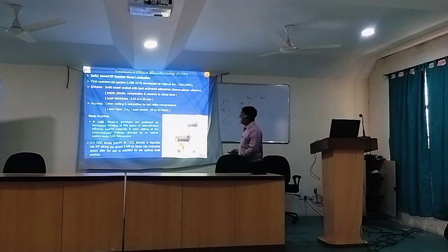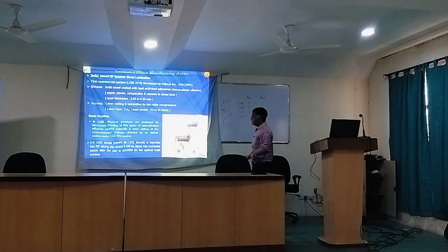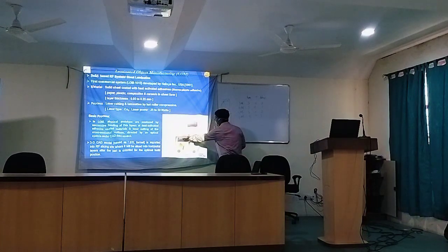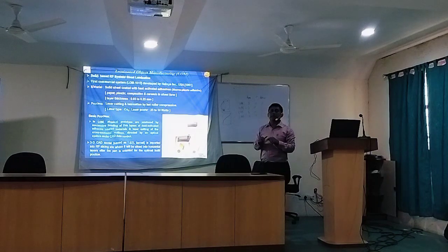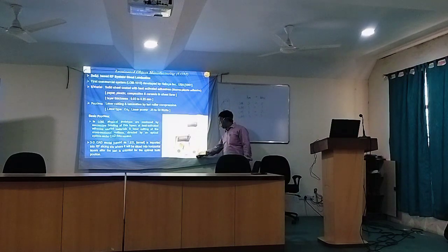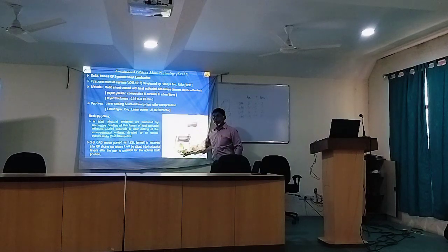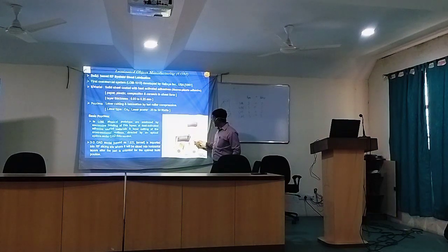The pre-processing part is the same. That means you have to develop the CAD model, save it in .stl file format, then do the slicing. After that, in this machine, this is the build platform. The build platform is initially here, and over it there is a white dummy paper. You patterned the dummy paper using say sellotape or something like that. From this roll, the material supply roll, you pull the paper over and clip it onto the takeoff roll. The fresh paper will be here, and below this paper there is adhesive.